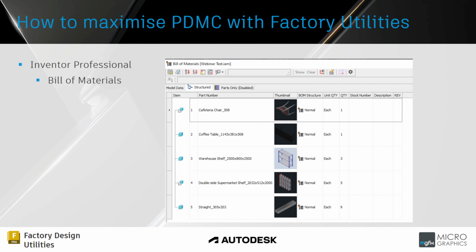So what I can do is swap out the level of detail, go for a high level of detail where I've got all my nuts and bolts, etc. in that, and then I can run my bill of materials and I'll get a full bill of materials down to the very last nut, bolt, and washer that I want. Okay, take that information, export it out to Excel, and then give it to the appropriate people to go and start either buying those nuts, bolts, and washers and creating and cutting all my steel work, etc.